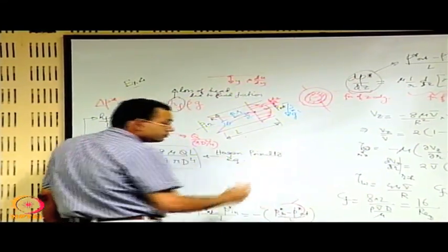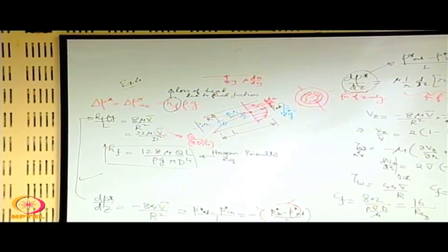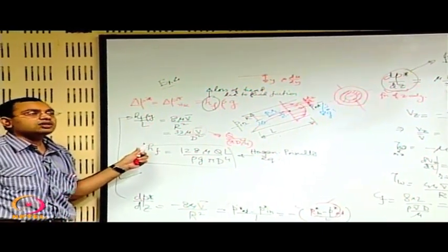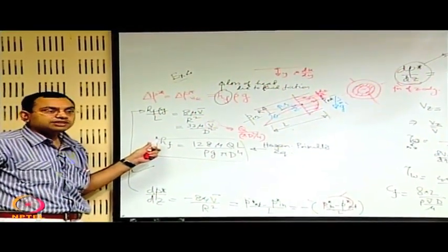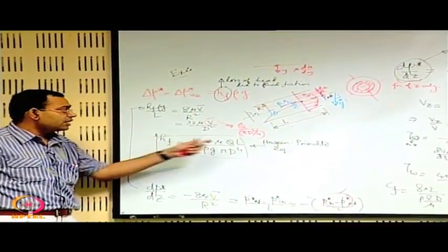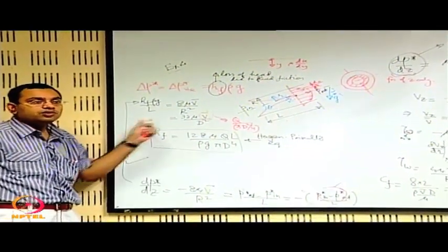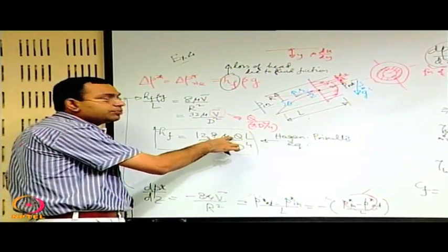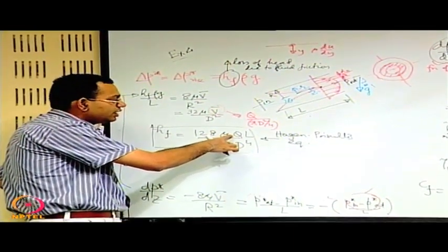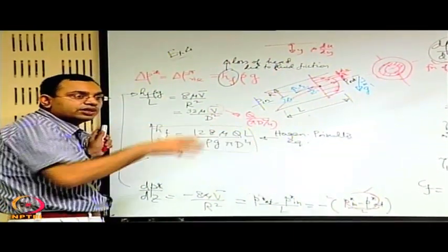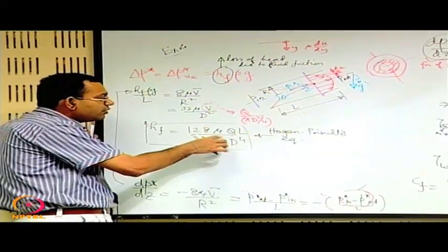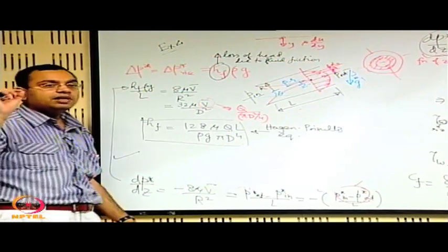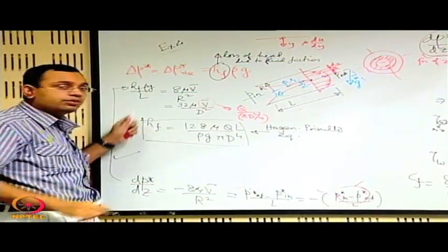What it gives is a direct indication of the loss of head due to viscous effects in the flow. If the flow had viscosity 0, there would have been no loss of head. We can see that the loss of head is directly proportional to the flow rate, proportional to the length over which the fluid is flowing, which is understandable, and inversely proportional to the fourth power of the diameter. So if you make the diameter very small, the loss of head will be very large.